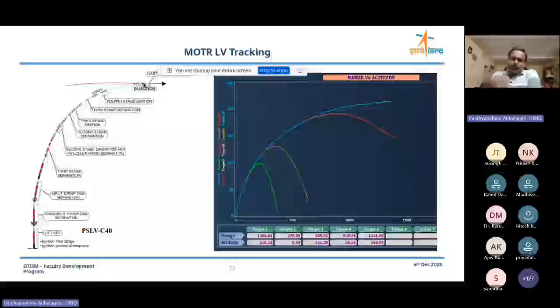So what we do is, with the left out fuel, we just passivate it. We call it as we left out that particular fuel, and that stage, all the pressured gas, pressurization, all those things are released. And from then on, that particular stage as a dead mass, it will be in the orbit. So that we call it as a rocket body. So any mission, if you see, what are all the number of useful payloads it is carrying? It may be one satellite, two satellite, three satellites. Those satellites will be put into a required orbit, and at last the final rocket body as a dead mass will be in the space.